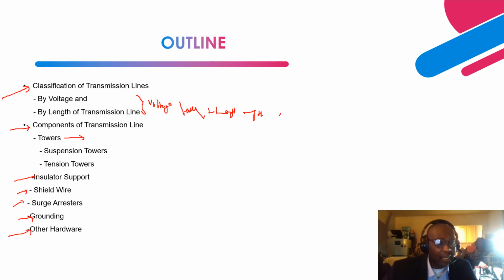Next is other hardware, right? A typical example is dampers and spacers. Dampers are the ones that dampen the vibrations from the conductors to prevent a phenomenon called wind clashing, where excessive wind force excites the conductor and can allow two conductors to clash into each other, right?